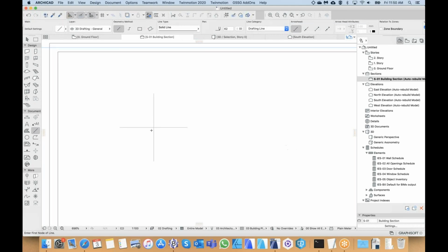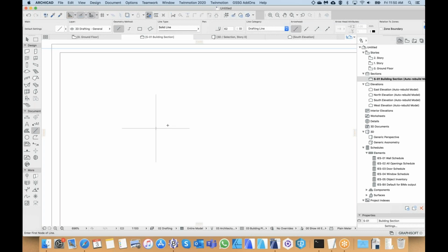Probably if you've only got one, it's because you didn't tap the Control key. Then your cursor will show a little plus to indicate it will make a copy. So as above, I wrote the command. So I'm going to do that again. Select the line, Control E, tap the Control key to make a little plus.